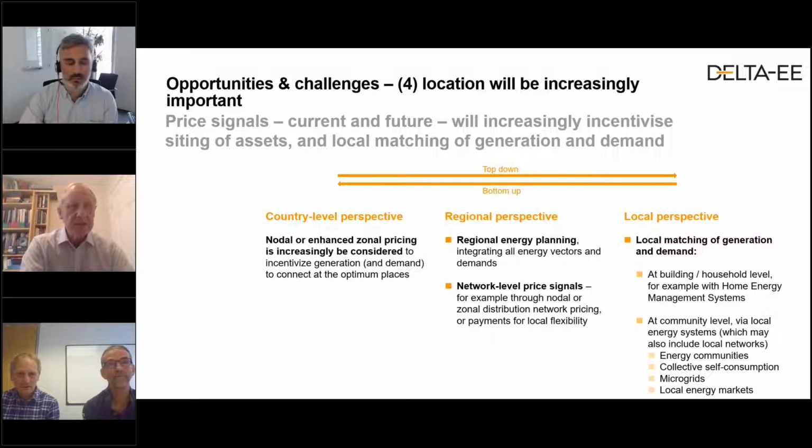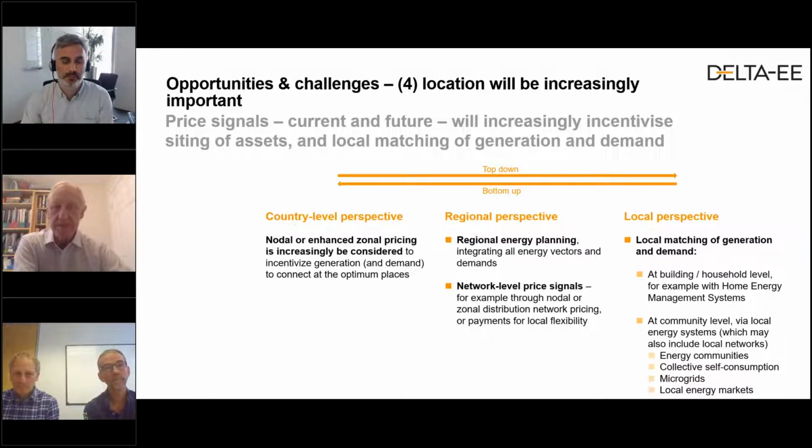Firstly, from a national perspective, one of the issues we have at the moment is that transmission, certainly in the UK, and I'm sure it's true elsewhere as well, even on the interconnected system of Europe, transmission boundary constraint costs are rising, and balancing the network is therefore becoming more challenging, requiring increasing levels of inefficient redispatch, because the wholesale market basically isn't exposed to locational signals to inform trading decisions in operational timescales. In other words, you've got generation which is constrained by transmission boundary constraints, but that's not reflected in the wholesale price at the moment. And therefore, national pricing can sometimes send perverse incentives to flexible assets that actually worsen the constraints.